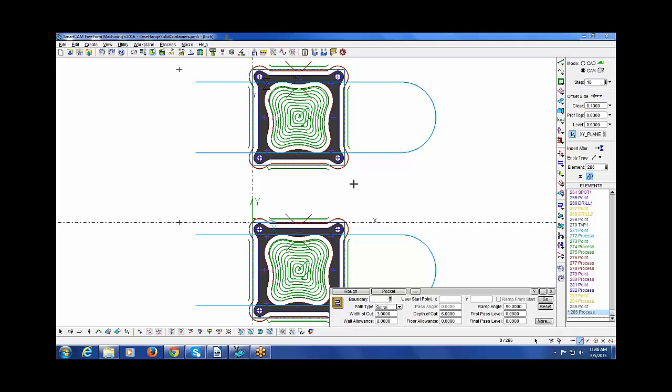Anybody else? Doug, do your custom tool graphics come into this library then? The custom tool graphics are still process model files that are out on disk in your folder, but the path and file name referenced by the item are stored in the library. So if you retrieve a tool and it has that information, it will exist in your job. It should pull that right in. Okay.